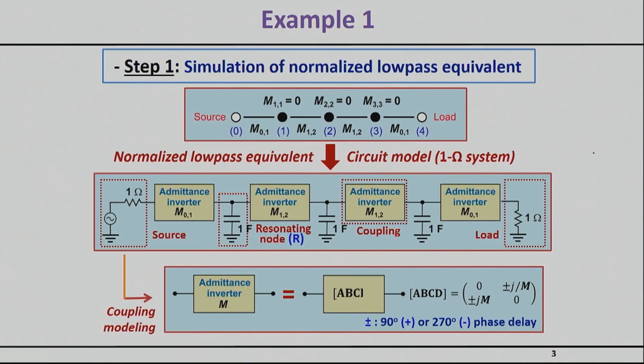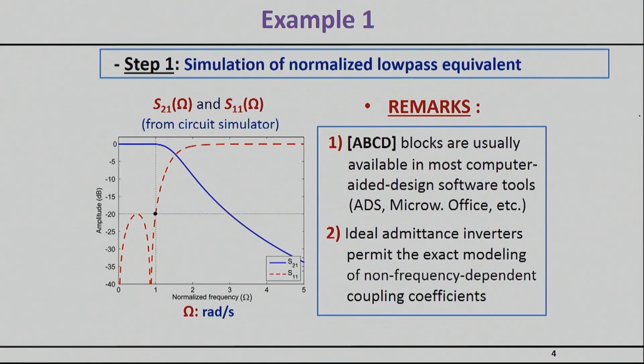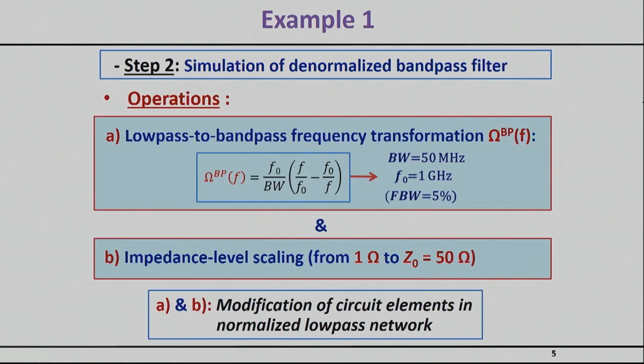Then we have learned that I can start synthesizing the actual circuit that will implement this by using inverters. Here are all the inverters we need. We need 4 inverters for a third-order filter, and then by using these normalized components that will very quickly become resonators once we denormalize from this domain to the actual frequency domain. I think I'm going to skip that slide. This is more of an FYI.